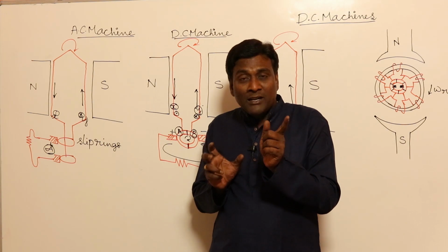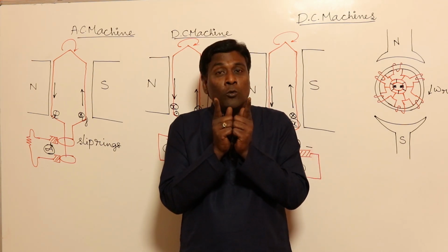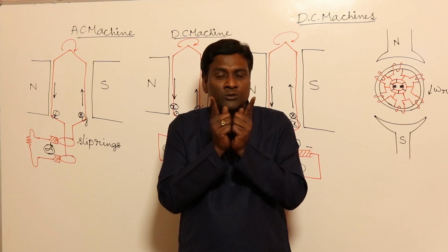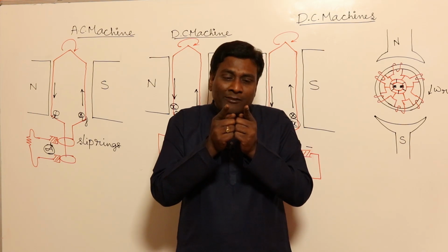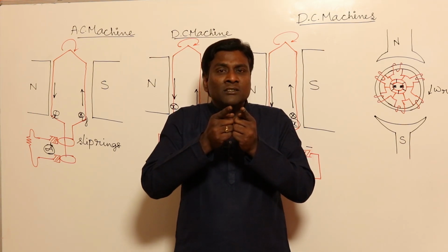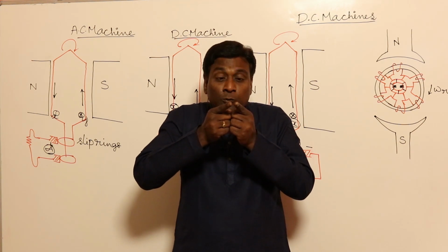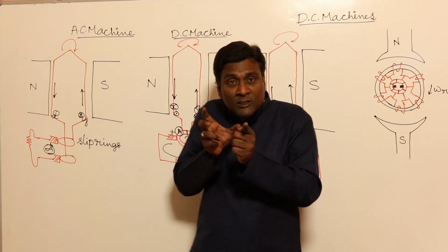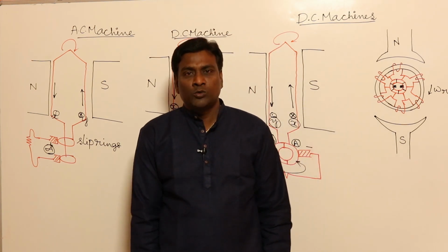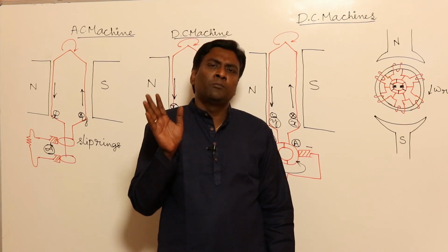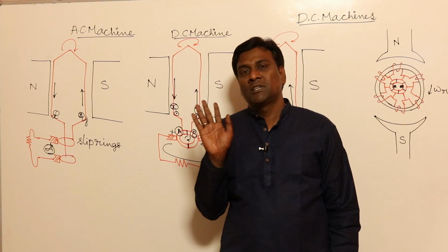But the applied voltage across these two terminals is going to be 100 volts only, so nothing will happen. But you are about to close the switch. So 1 centimeter will become half centimeter. Half centimeter, 15 kV is sufficient. Maybe it will become 1 mm. 1 mm in the sense just 3 kV is sufficient. So you are about to close the switch. At one instant, this particular 100 volts is sufficient to strike the spark. So conclusion is very simple: without spark we cannot make or break the contact.